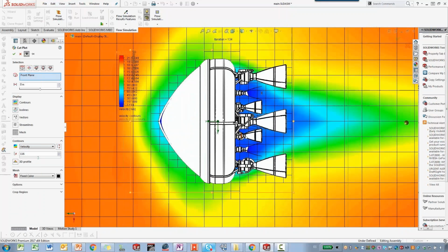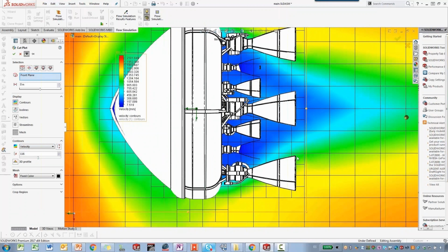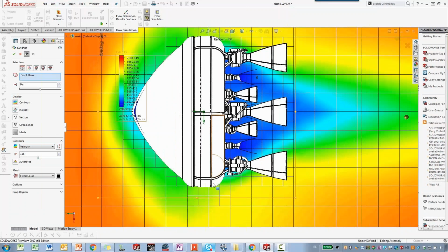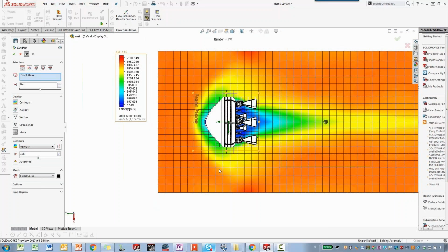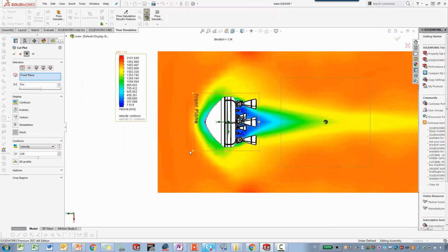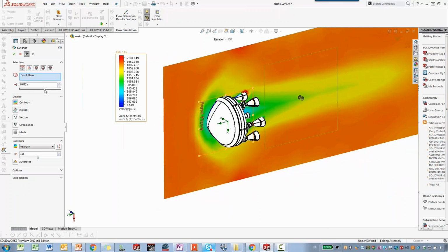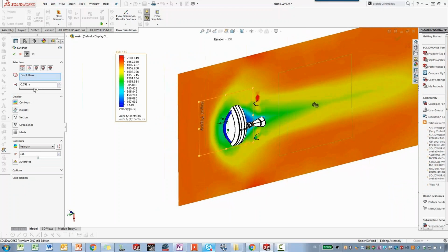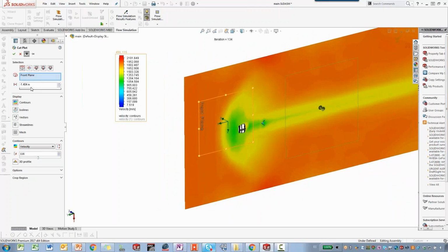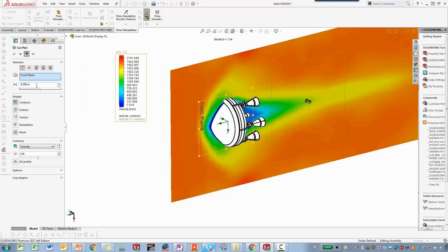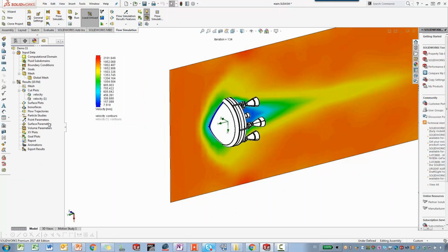One of the good options as well is to show the mesh. Where will the mesh be located, as a defined mesh or maybe an adaptive mesh? I mean a refined mesh. And also we can change the offset, and one of the good options is that we can animate the offset distance later on. So we can use SolidWorks Motion in plotting the animation of SolidWorks Flow Simulation.